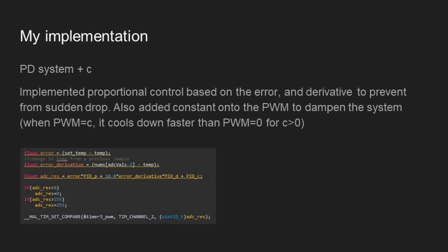You can also see that I capped the ADC value from 0 to 255, because you can't have the ADC value lower than 0. And for my ADC, I have an 8-bit ADC that I implemented, so the max will just be 255.